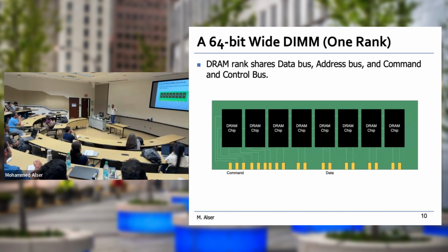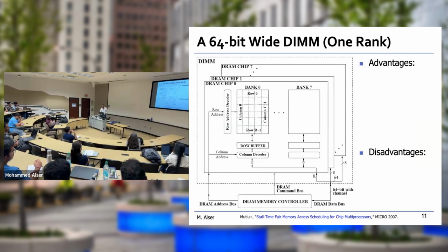That's why even if we increase the number of chips, we cannot do anything with the throughput. We still get 8 bits per chip per clock cycle. But at least we can fit 8 of them within a rank. Now that is for single rank. We can, of course, have multiple of those ranks, and each of the rank have 8 chips, for example. In this way, we can get things in parallel.